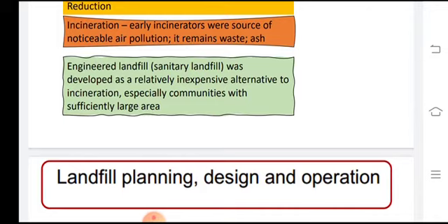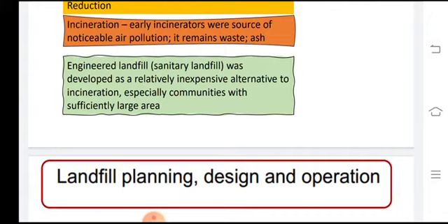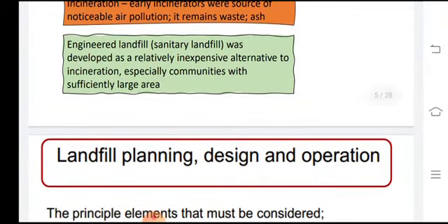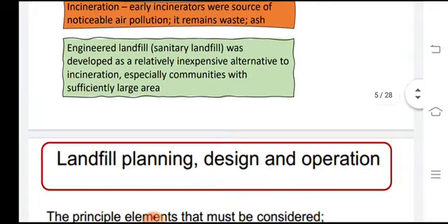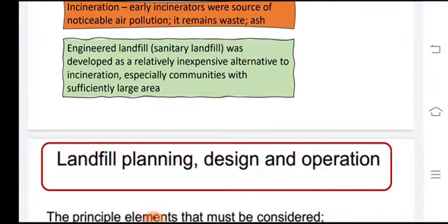So first of all, one option is the landfill dumping placement. The second option is to use it as non-bearing construction material. It is also one of the options for the residual ash, because it is going to have a high level of bearing capacity, and it has comparatively high compressive strength. So that's why it is very useful as a construction material, particularly at places where much heavier loads are not expected, for example in parks or in landscaping. Such things are easily done.